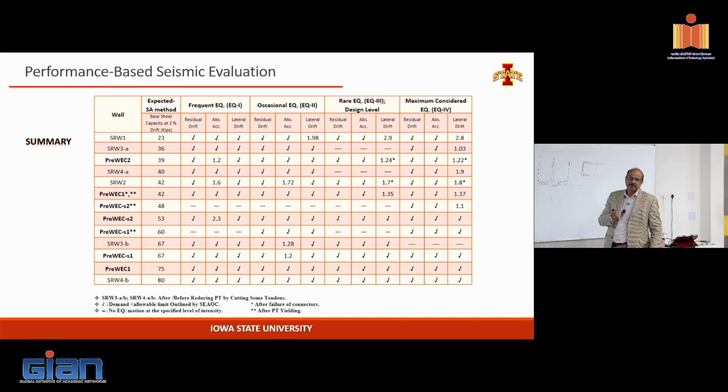But in the same question, you go to the bridge world. I don't know about here. In the US, bridges and buildings are worked like this. They will have like 300-meter unbonded post-tensioning going from one end to the other. Nobody questions. You put it in a 3-meter wall, they say, oh, why are we doing this? But even here, unbonded is not very common. Yeah, that's what I'm saying.